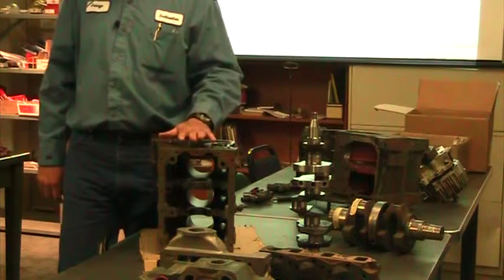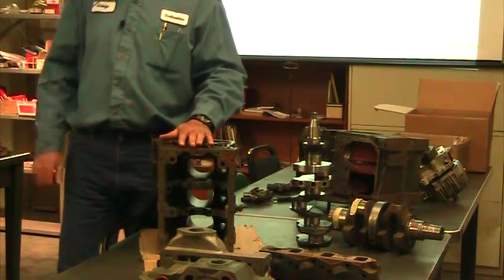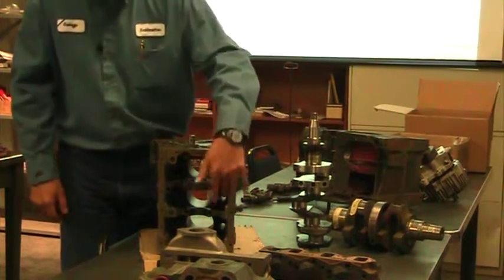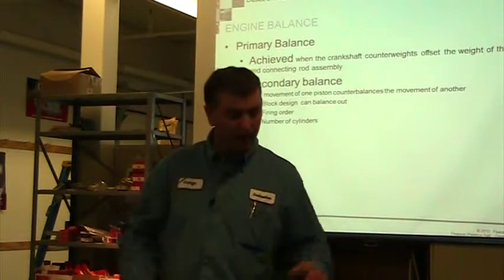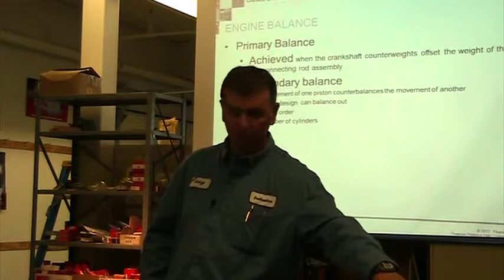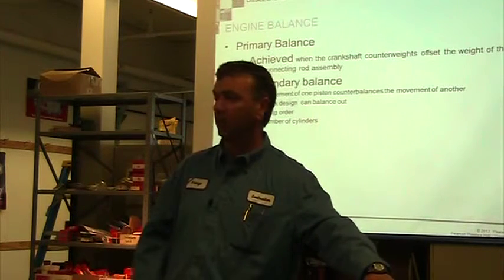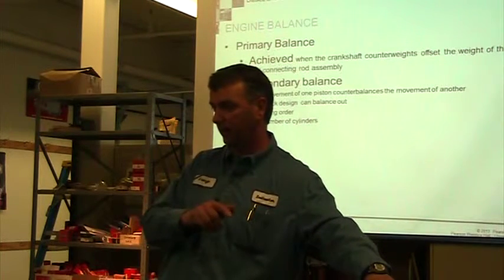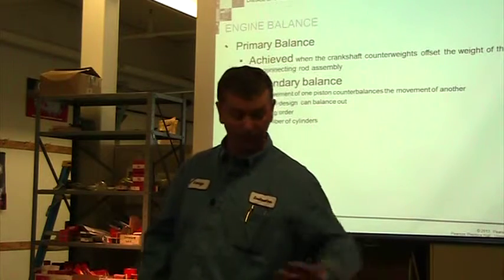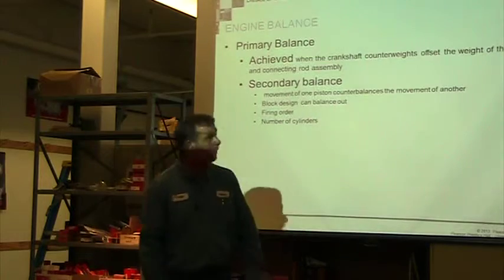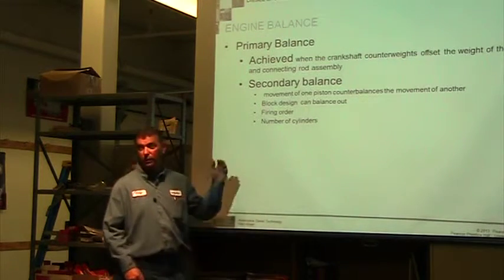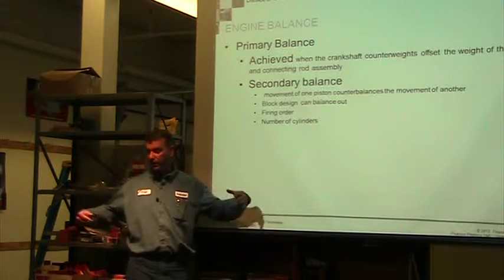If this is a 4-cylinder engine, 4-cylinder engines are not very well balanced, and it will be very common to have secondary shafts in here rotating to help smooth them out. 3-cylinders don't have that. So that's one of the reasons why we see so many 3-cylinder engines in this industry, because of how their balance is. Not as balanced as larger cylinder counts, because the more cylinders you get, the easier it is to balance them out.